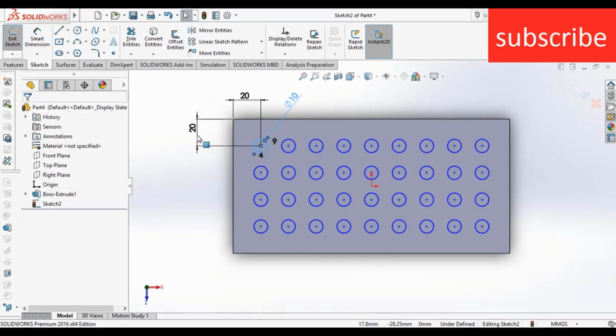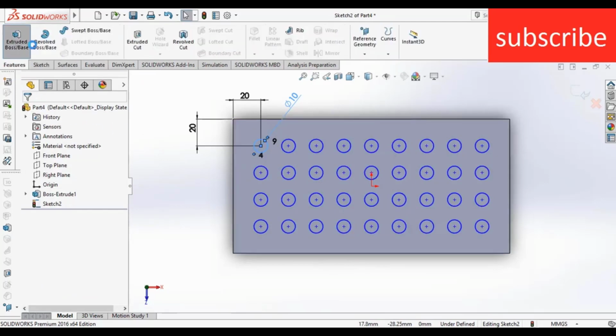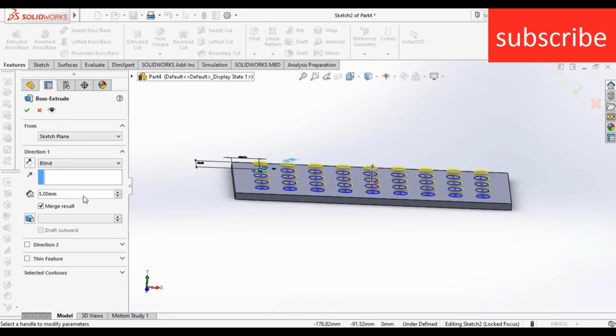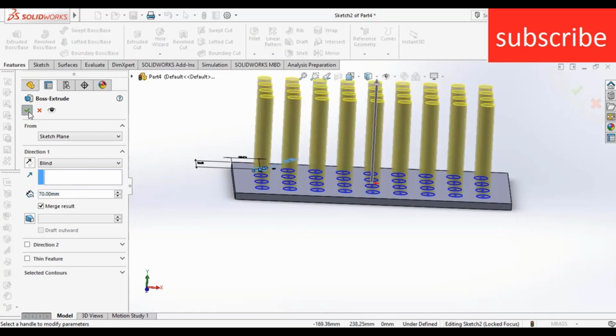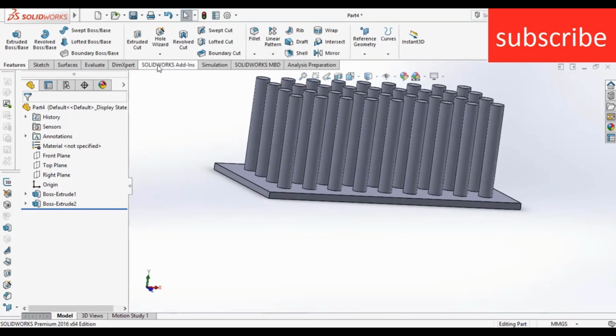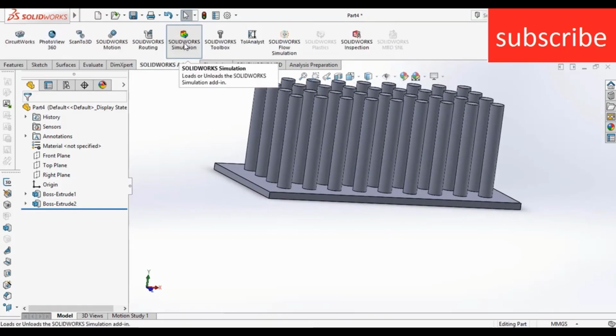Here I drew the shape of my fins. Basically I am using circular fins. Now extrude up to the length of 70 mm. Click OK. Now go to SolidWorks add-in, click on SolidWorks simulation.